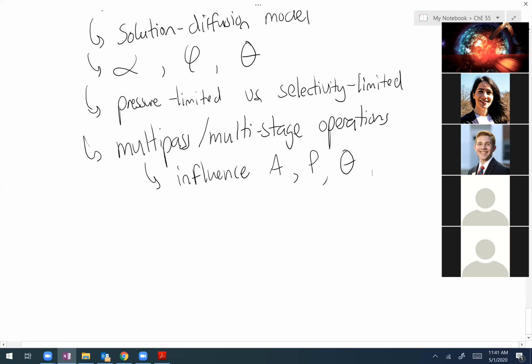And so that's the in between, where both the pressure ratio, in which the module's operating, and the selectivity, which is being limited by the membrane, are both going to be key factors. Then the flip side is when the pressure ratio is so high, you're not going to get a better separation out of the system because you're just going to be pushing more material in total through the membrane, but it's not going to be more selective through the membrane, if that makes sense.